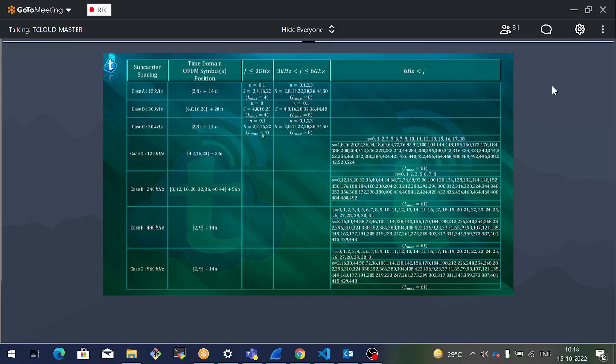And the mobile can also detect Lmax, how many times it is getting repeated in a subframe. 4 times or 8 times, the mobile would be able to find that out, because each SSB block contains the same mechanism: PSS, SSS, and all the other channels, including the null arrangements.